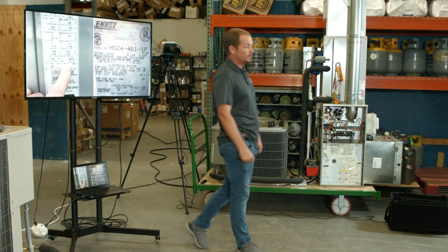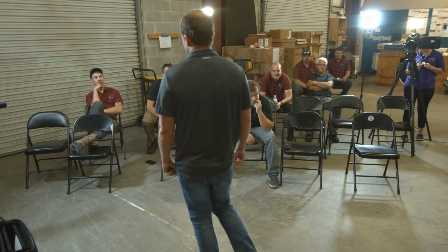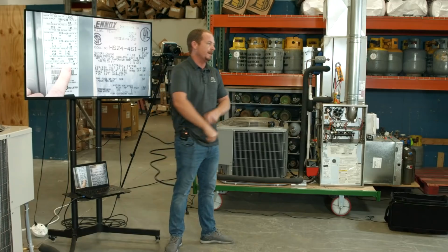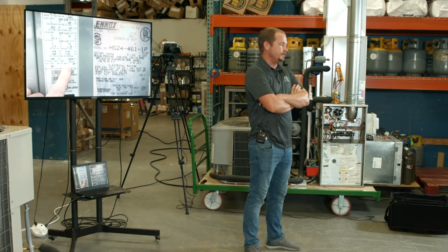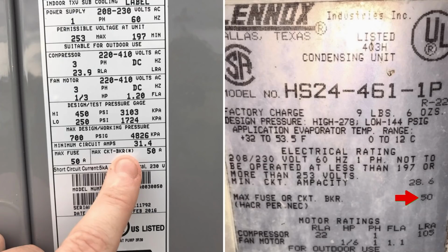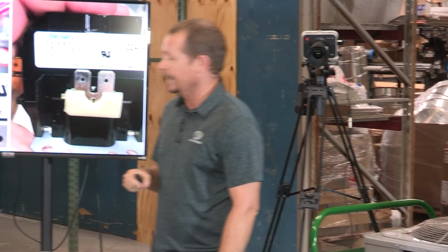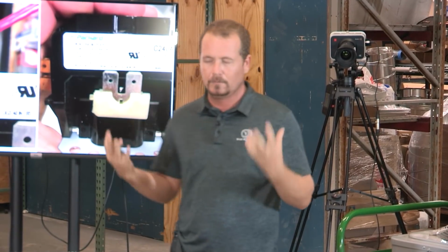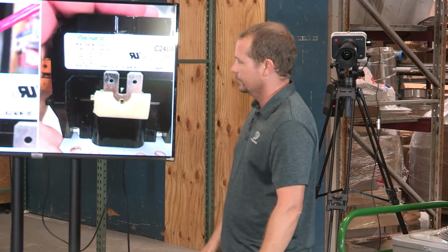Does that mean you couldn't put in a smaller size? You could put in a smaller size, only because even a breaker can have an ampacity. But yeah, you could potentially put anywhere from a 35 to a 50 in there. Now, inspectors aren't going to let you because they don't understand what they're looking at either. So don't even start with them. You circle it. But here, we could have a 50 amp breaker on a number 10 wire, and it would be completely allowable by the NEC. Again, go back to the NEC or look at Mike Holt's videos on this if you think I'm crazy, because a lot of people will argue about this, like every single time.